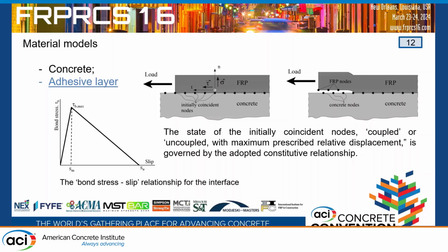So this limits the application of the model to normal strength concrete. If you need to apply the model to high strength concrete, we also need to define the adhesive layer opening. Maybe a good solution would be to also model the adhesive layer, where you have a bond failure. Yes. In the future we will try to make a thin band. Right, okay, I got you. Maybe it will be better, but we should try.